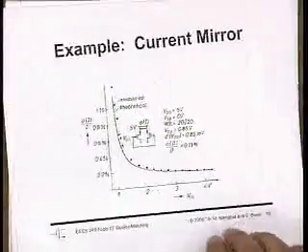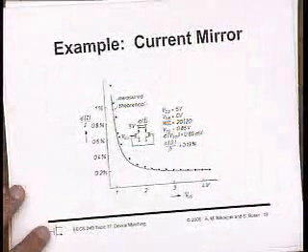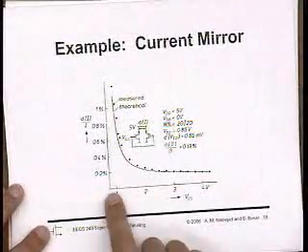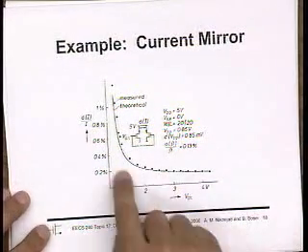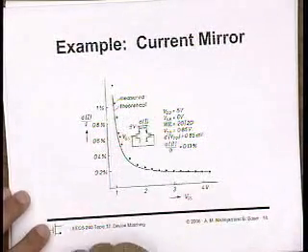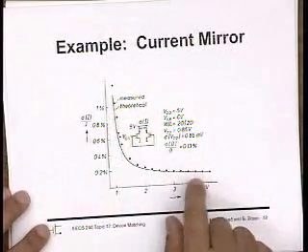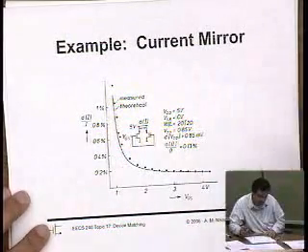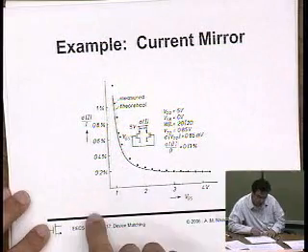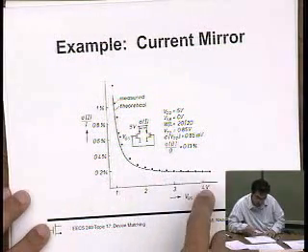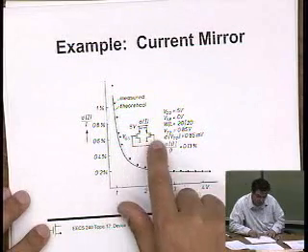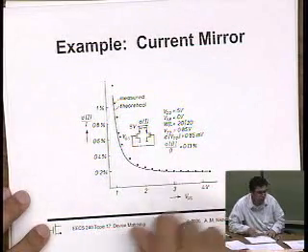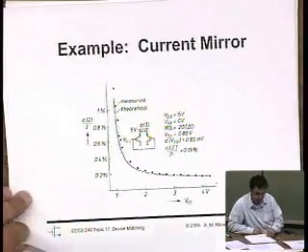So again, these are just some curves showing you, if you're designing a current mirror, obviously you're going to bias it with high VGS. And this is a measurement versus model mismatch. You can see that this simple model with these coefficients that we looked at very accurately tells you that as a function of VGS and as a function of geometry, for this current mirror, you're going to get 0.2% matching.